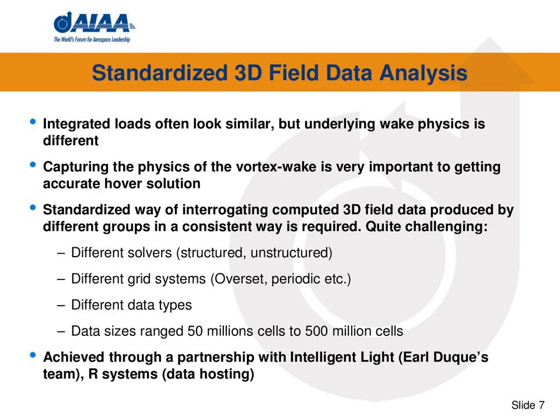So, as I said, the need for rotor hover prediction and the underlying physics of the wake are very tightly integrated. What often happens is, when you have several codes looking to predict the performance of a rotor blade, the integrated loads often look similar, but the underlying physics basis is completely different. Trying to correlate how well the wake physics is captured to the ability to consistently predict the loads is of critical importance, and that's why we put together the idea of teaming up with LDK and Intelligent Light to see if we can standardize integrating the computed 3D fields.